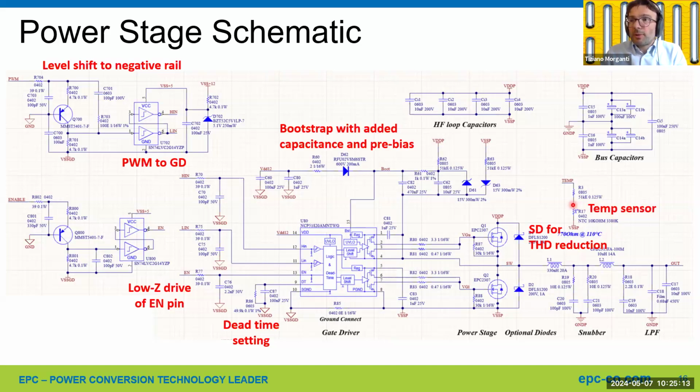Then we have a temperature sensor for over temperature protection, which is connected to the source of the low side FET to have it very close coupled to the FET.